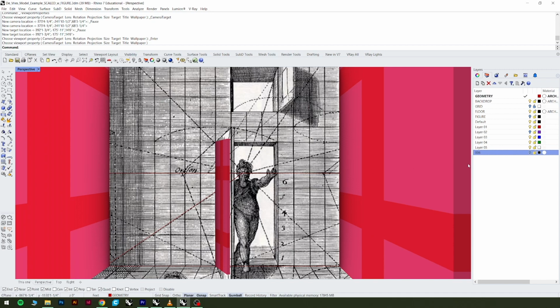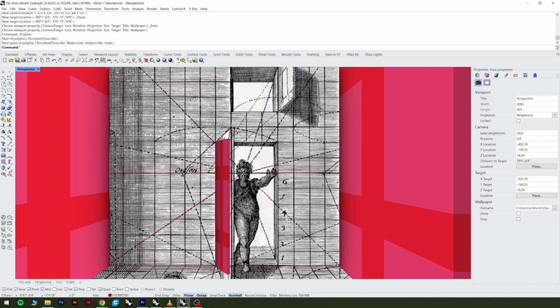This horizon line is centered to my screen, and the vertical line, if I had drawn it again, which I can actually do right now, will be centered to my screen. Or actually I can't do it because you'd want to be in front view. And you'll have to toggle back and forth between front or right, or whichever view you are aligning this to. But so here we go. I'm going to go over here to my properties, and I don't have anything selected. I just am here in Rhino, nothing selected. I'm in the properties window, and now this is actually the view properties, and I can change the lens length. So I'm going to change this to a common camera millimeter.